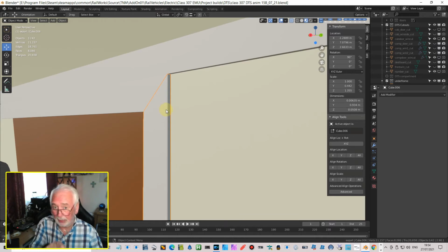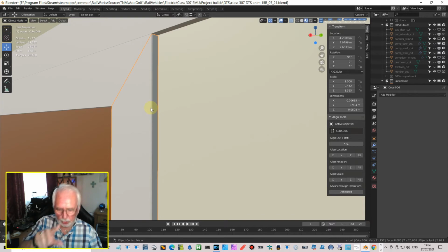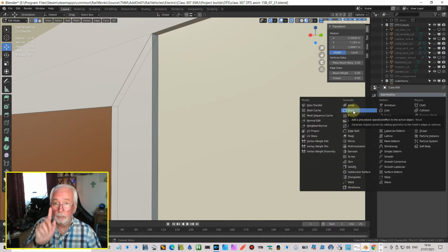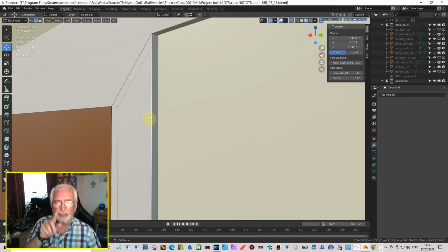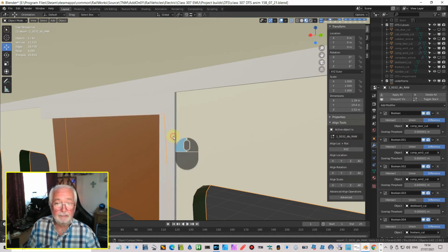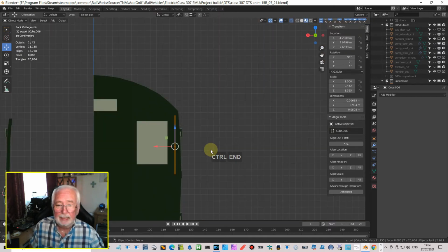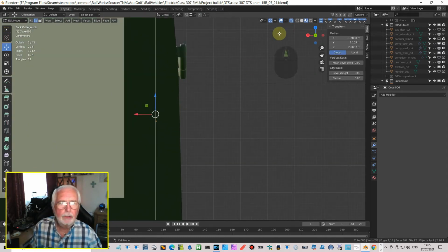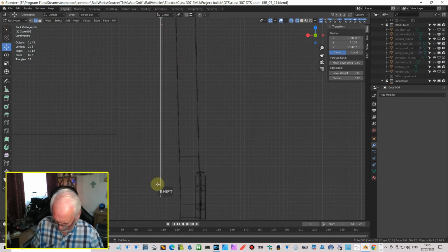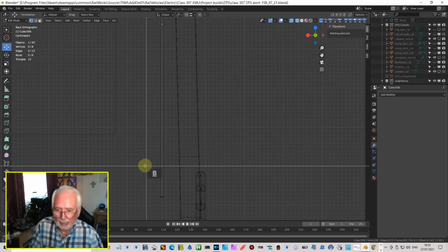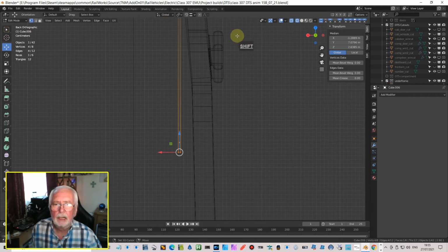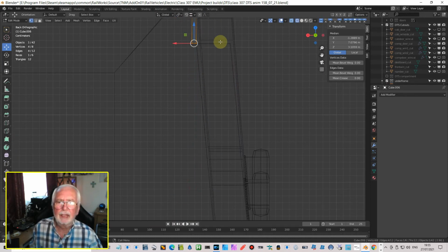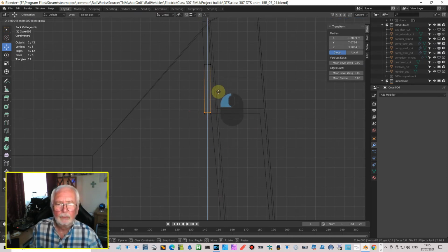Now the bevel there is a destructive bevel, i.e. I've affected the actual cube there, the actual mesh. Really what you could do with is using a modifier, and you do have a bevel modifier that you can use. I'll show you how to use that, but once I've actually shaped this piece of beading, because at the moment it's straight, and if we come here we can see that the actual carriage here curves, so we need to change that. So let's go into wireframe mode, okay, and let me go into vertex mode, deselect, let's grab these, pull them up, okay, right up here, and then what we're going to do, we're just going to extrude and shape it as we go down. So let's take it up to there, and yeah, that is our first